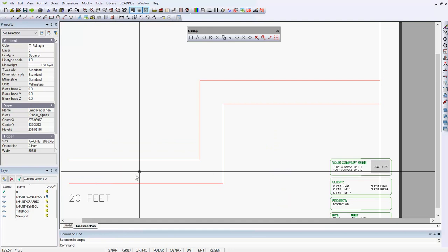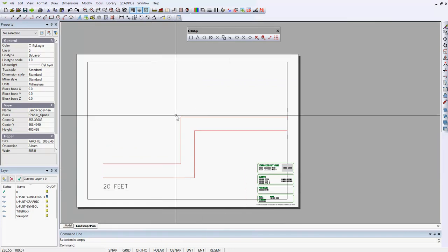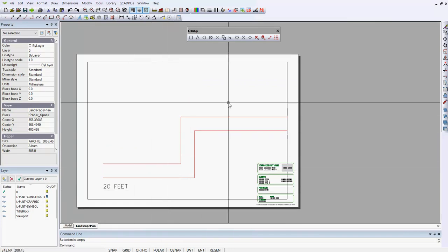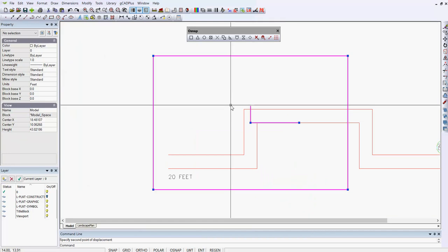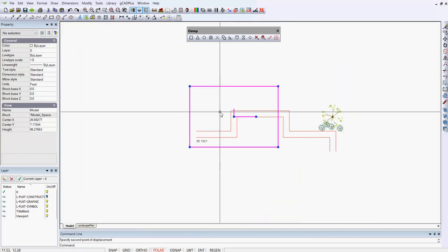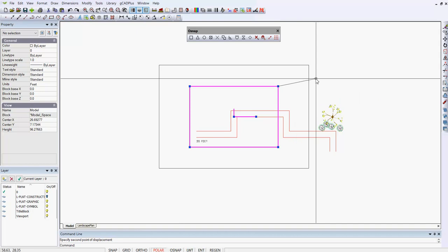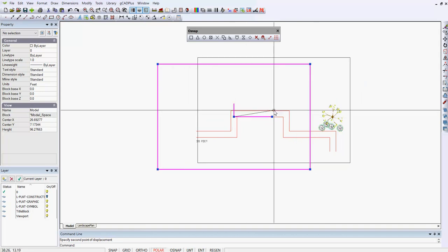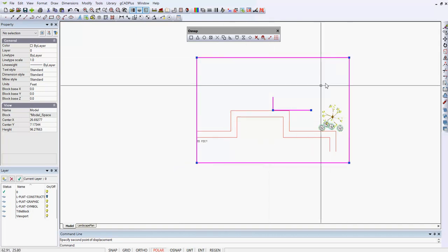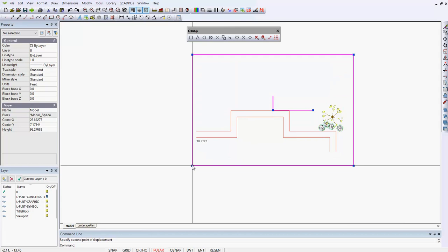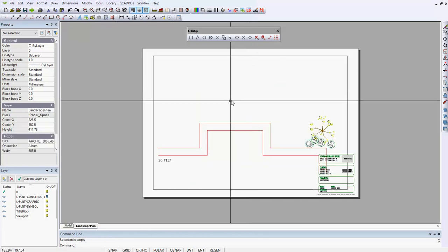And if we come over here, and you'll see now we're zoomed in just on that bottom left area, I double click and scroll out using the wheel of my mouse, and I can arrange what I see in that layout space just by changing this magenta box, right clicking and display it on the layout.